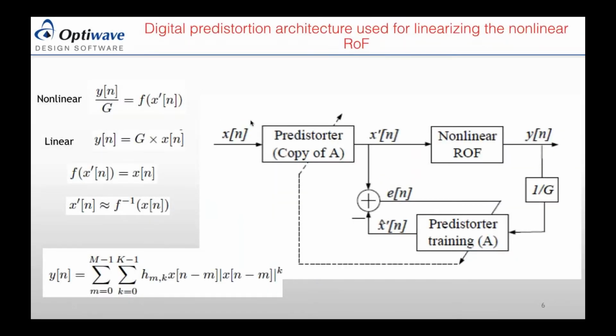The second slide here shows the digital predistortion block. Traditionally, if you have any input signal, and imagine that you don't have this copy right now, the link nonlinearity, mainly because of the Mach-Zehnder modulator, will generate intermodulation distortion. It could be the third or fifth intermodulation distortion that you will see at the output. Now, if we look at the nonlinear equation right here, if you divide the output signal by the linear gain, you will end up with a nonlinear signal.